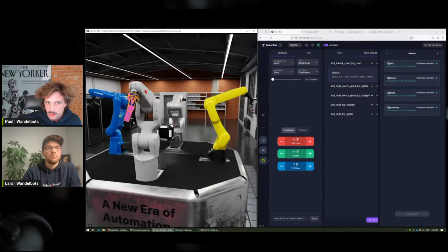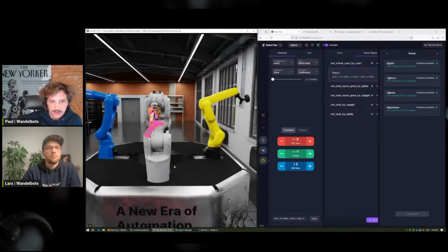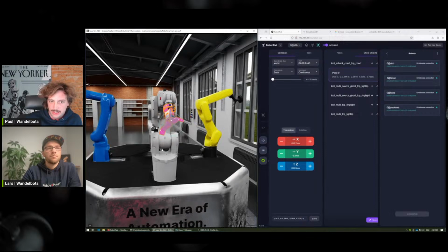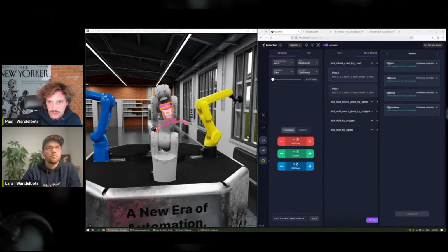It might be a tool or a workpiece. And this object comes from the USD file. And we are constantly reading its position and directly converting it into robot poses. So you can see I can drag and drop and rotate this 3D object in our Isaac Sim scene. And after that, directly move to that position. For us, this is really the fastest and easiest way